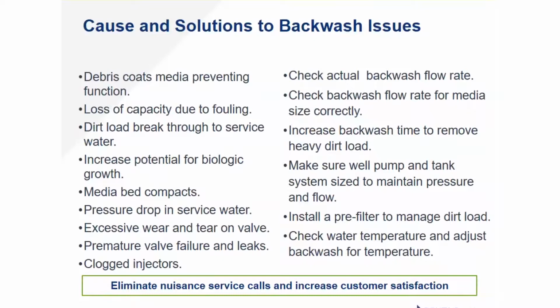This is at a point where you can't just backwash the resin clean again, you really have to refill and start over. When you could have just had a good backwash setting at the start and not had this issue.